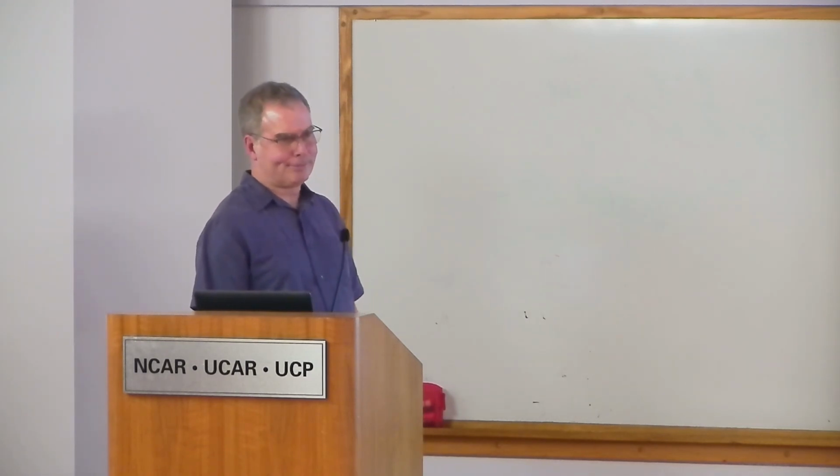Okay. One quick question. What is your top boundary condition? Right now it is du/dz, dv/dz is 0, and w is 0, up at 500 meters. 500 meters. Yeah. I use a stretched grid, so it's well taller than the wind tunnel at this point.